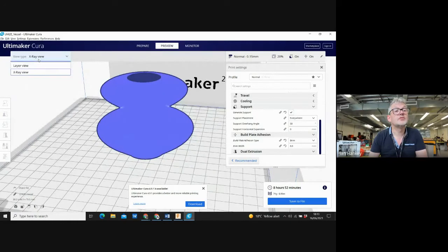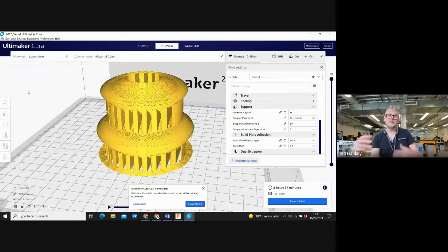I tend to go through my layer view because it's possible, if we don't get our models particularly right, we can end up with part of it being a solid and part of it just being a surface. It looks like a model, but it's only a surface. And as Owen explained last week, if we draw let's say a box, draw a square, that plane needs to be extruded before it's actually in the real world. It can be printed. If it's not extruded and it's just a plane, it doesn't actually have a physical thickness, so it can't be 3D printed.